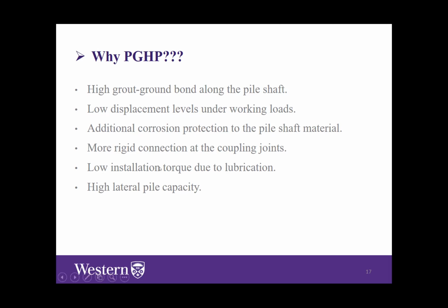Besides, by increasing the pile shaft diameter with this additional grout column, we increase the lateral pile capacity of the helical pile.